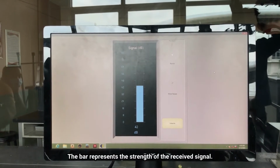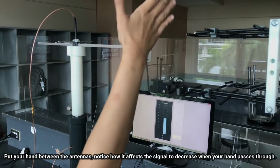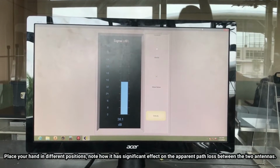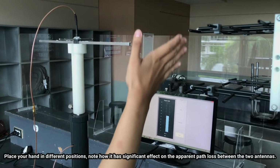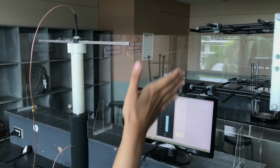The bar represents the strength of the received signal. Put your hand between the antennas. Notice how it affects the signal to decrease when your hand passes through. Place your hand in different positions. Note how it has a significant effect on the apparent path loss between the two antennas.